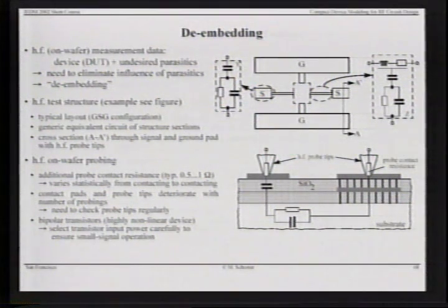And on top of that, when we have this on the wafer and we probe this directly on the wafer, we usually have contact resistances from the probes to the metal of these pads. Underneath the pads, again, there is an oxide, there's an isolation, and there's a substrate coupling network also between the signal pads and the ground at high frequencies.